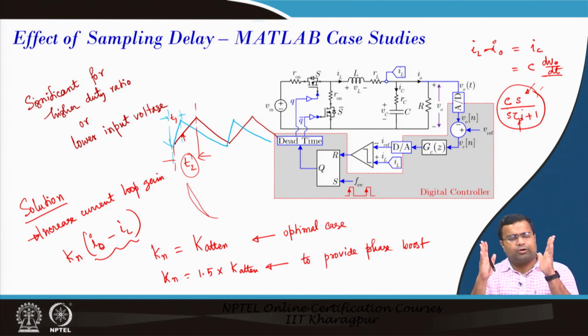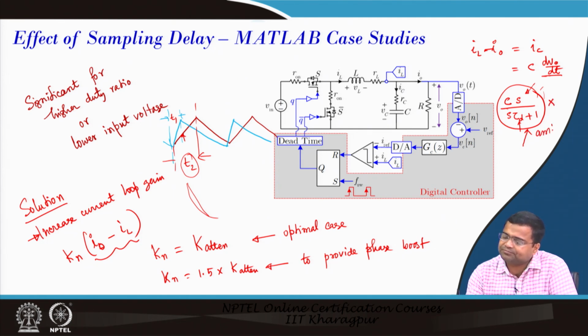It is a large signal model, so there is no concept of frequency response phase plane, but if someone wants to think in terms of phase boost and phase lag: the delay will cause a phase lag, and the phase lag will cause more oscillation or more overshoot and undershoot. If you want to reduce the phase lag, you have to provide some additional phase boost, and that is provided by this additional term. So, we need to amplify this factor.